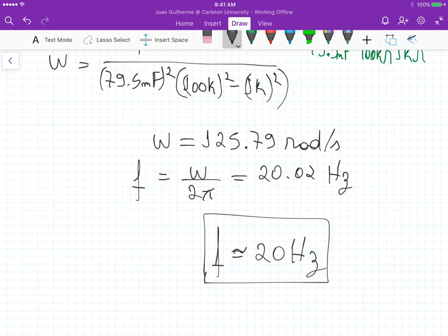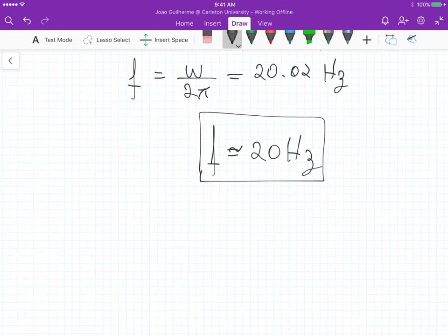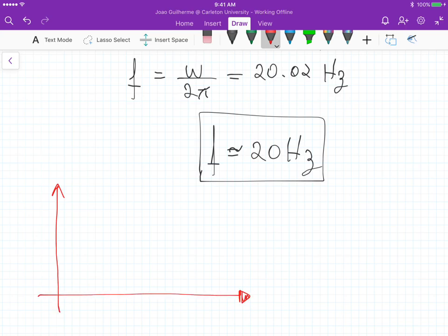Okay, so there's another way to verify this condition here, which is that because we have a transfer function that increases by 20 dB per decade, so let me draw here. So this is the magnitude of the Bode plot, and let's say here we have 0 dB, and basically we know that at very high frequency, the gain is 40 dB.